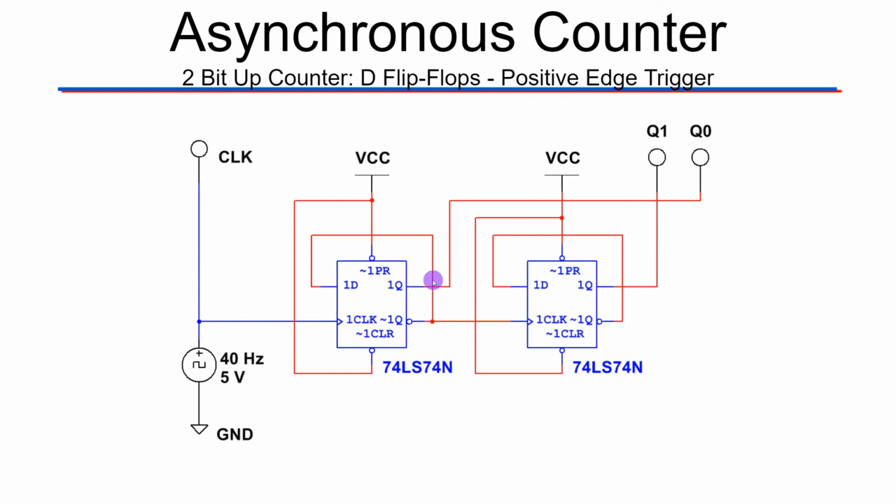All right, so some other things to notice about this design is how we are actually showing this count. Each individual flip-flop is saving a single bit of information, which is going to be a single unit in our binary number. So our first flip-flop here, we have Q out, and we notice that this is wired up to Q0. And again, it's important to note this is actually our least significant bit. The way we want to design this is so I can look at this value and read left to right as we normally would a binary value, with our least significant bit over here on Q0.